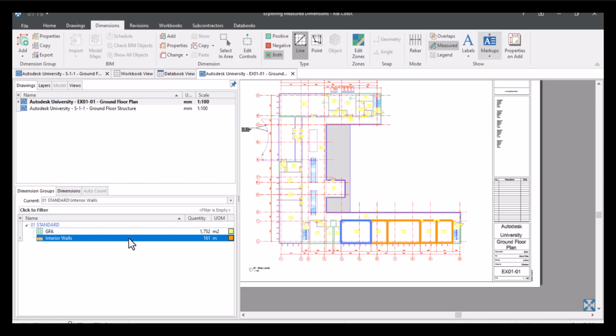So when you're using these quantities, although you've only measured the length of each side of the room, you've actually got your wall area. So if you needed to do your costs for plasterboard or painting, for example, then you could use that quantity from your wall area, as well as you could use your length for items like skirting or coving, or whatever you need to. So the beauty of measured dimensions is just basically collecting all the information you need to complete your cost estimate. So you're not limited to just one measure type, you've got multiple quantities that you can draw from.